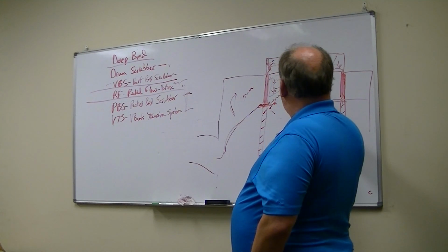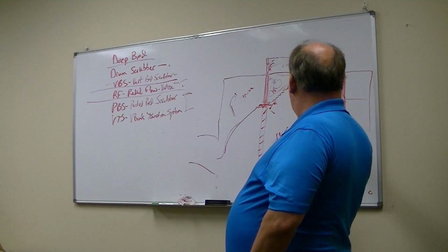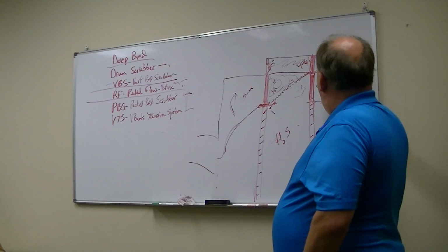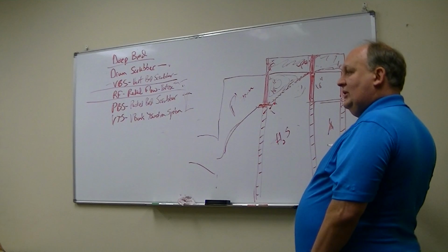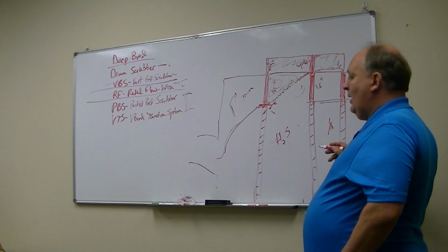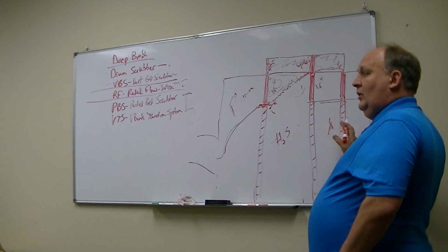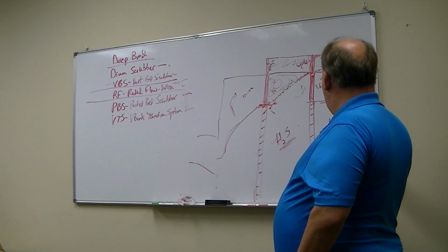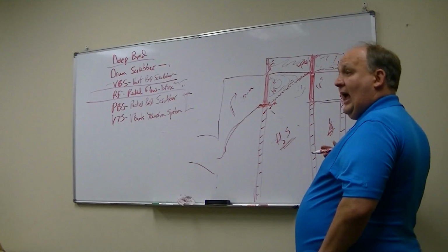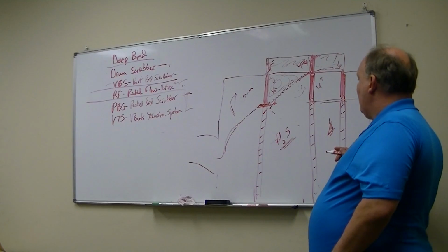So how we found out about this issue is the customer put only our media in this section here. They were having a problem polishing the odors. They were doing a great job of taking out hydrogen sulfide, but they weren't doing a good job of taking out some other gases, specifically one called dimethyl disulfide.